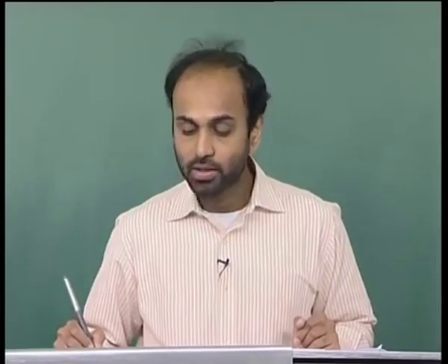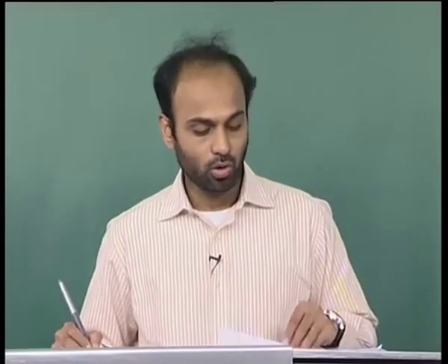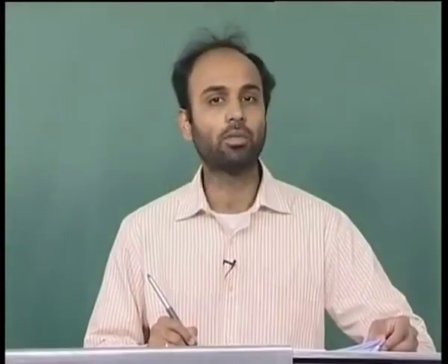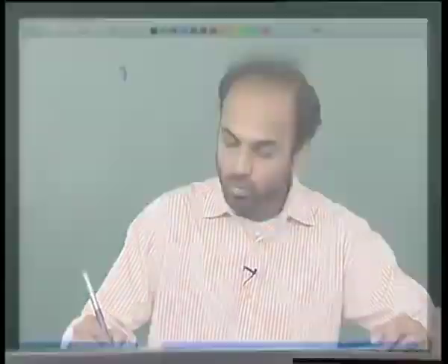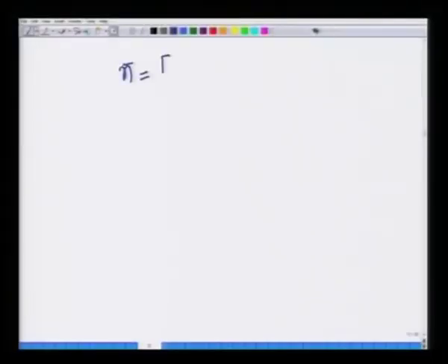Now, let me illustrate to you another technique to compute the power in the noise, because this is important, because we will do this manipulation several times. So, let me illustrate to you another technique to compute the noise power, which is also useful to you in many other contexts. So, we said the noise vector n bar is nothing but the vector n1, n2, so on up to nL. The noise vector n bar contains L components, that is the L noise components across all the receive antennas in this multiple receive antenna system.